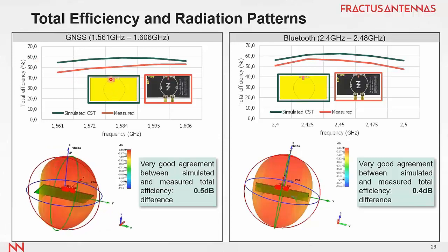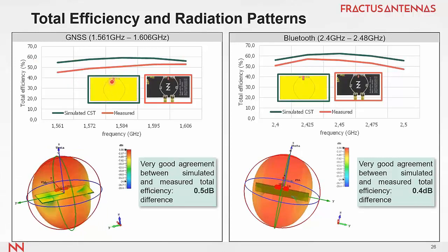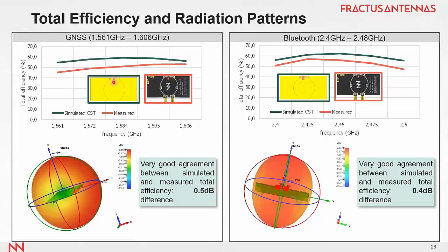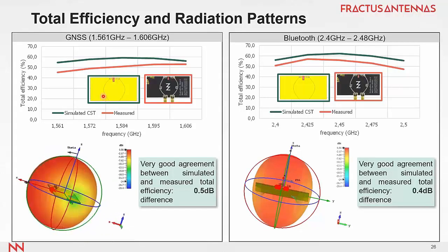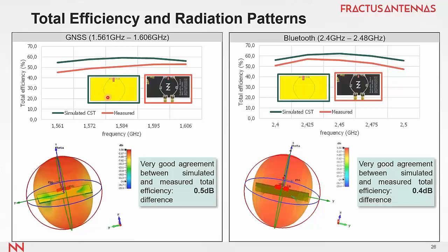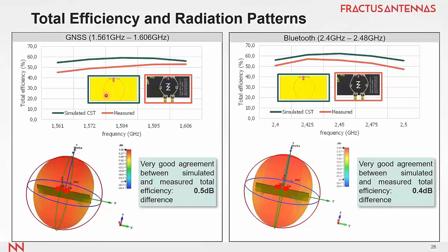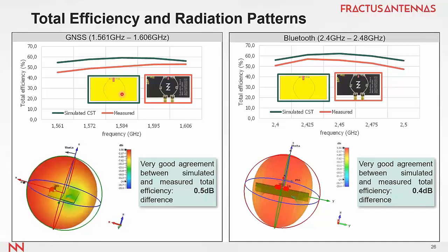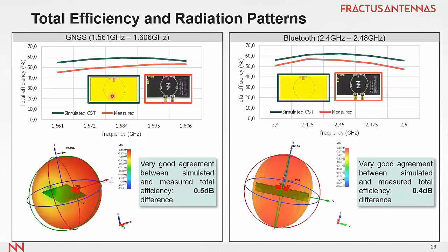In this case, we have also modeled the transmission lines, because in some cases the front end module is not close to the antenna booster. In some devices, there is some distance between the antenna booster and the front end module. So in those cases, we can use transmission lines like these microcoaxial cables, and these microcoaxial cables can also be taken into account in the simulation process.